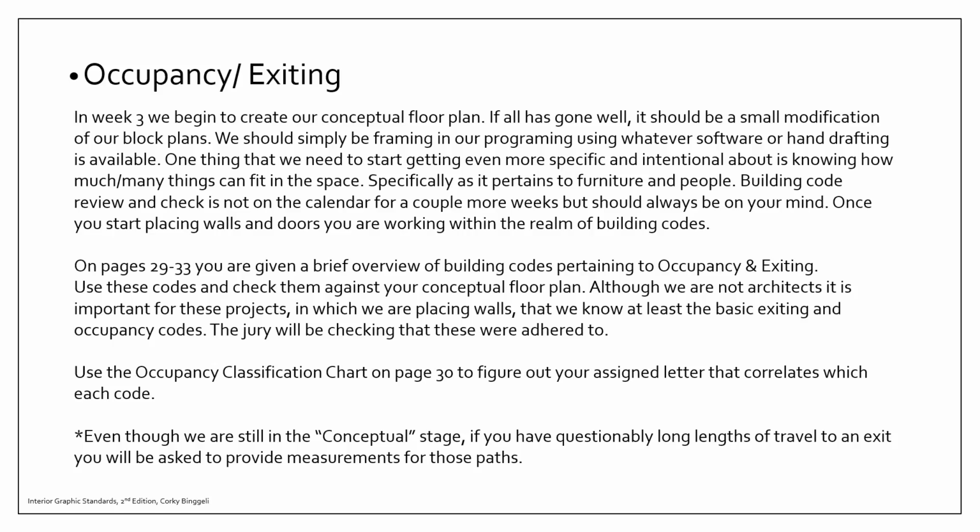So you have to start from the far bottom corners and then factor in the footage to turn a corner around some of those furniture pieces and then go out the straight line of access to the door. So as you're adding furniture or changing your layouts, you need to be considering if that's affecting your egress travel path in any way and add that to the footage that's required.